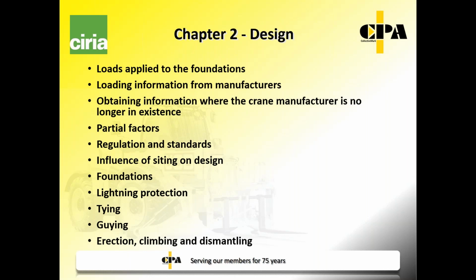These are often 500-ton cranes, which are extremely large and have high outrigger loads, so therefore the design needs to take account of the foundations for these mobiles.